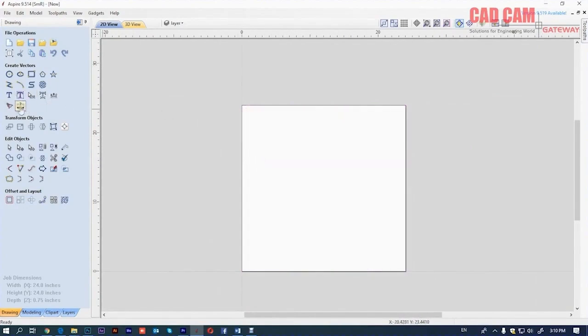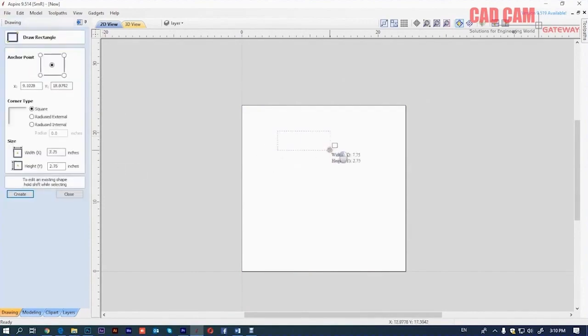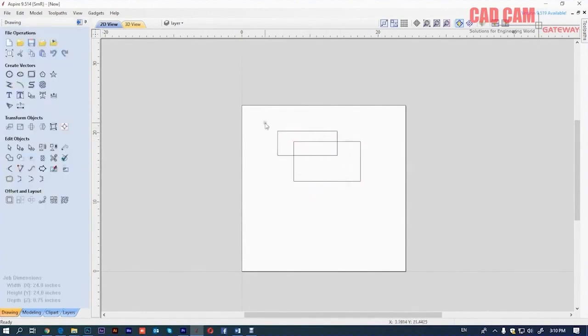Along with this, we have another command available here. You have already seen the icon group and ungroup here. Here you have these 3 commands which we have already discussed. But let me briefly explain them. I have placed these 2 objects one above the other in a rectangular shape. If you select both objects and use this first command, weld, it will remove the overlapping area. The area that is overlapping will be removed from it, and the outer layout will remain as it is. All the remaining intersections will be removed.